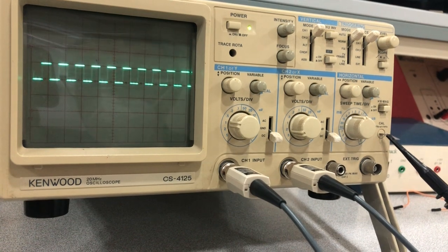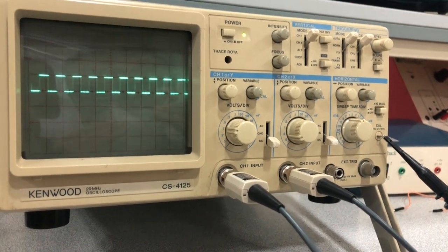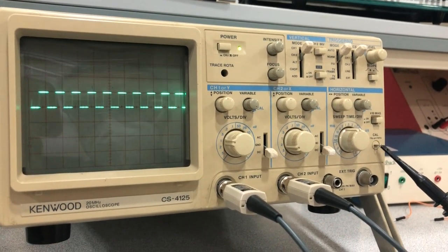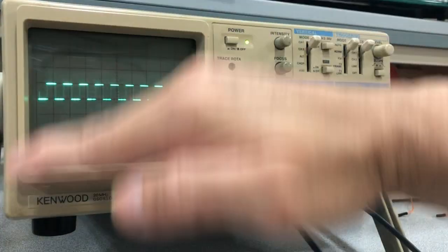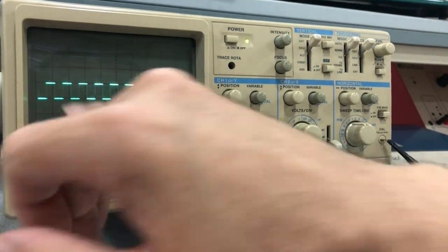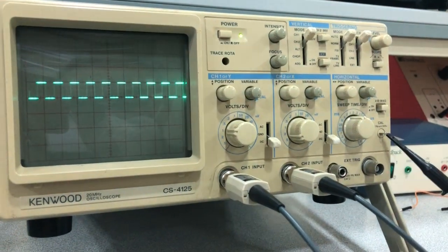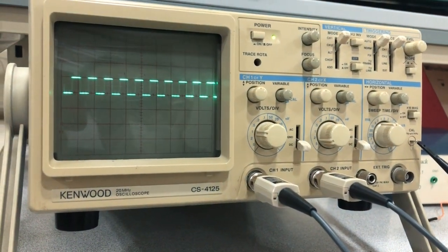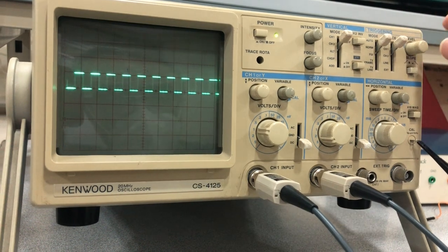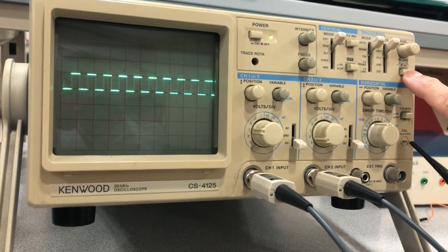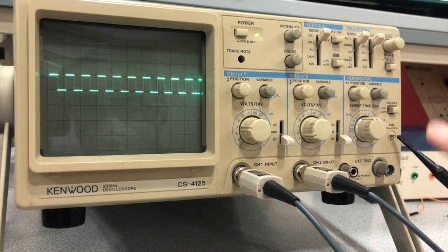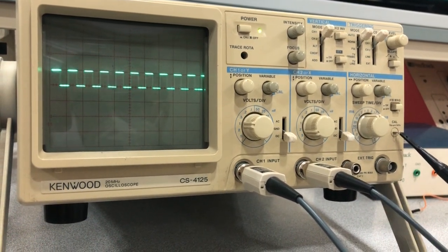What we call a common point between the horizontal line, which is imaginary now, and the signal. Some advanced scopes, digital scopes, will show it to you as you move this knob. They will show either an arrow on the left, or they show a horizontal line and then it disappears, and they usually make it a dashed line or whatever. Now you can start plotting from either the negative slope when this is pushed, or you take it to the outside and start plotting from the positive slope.